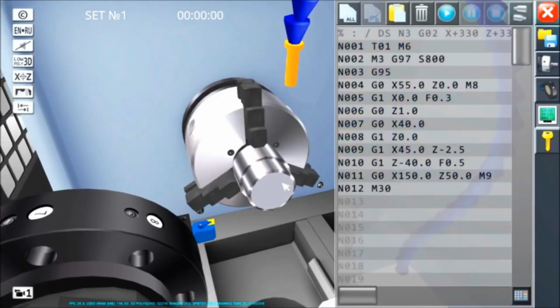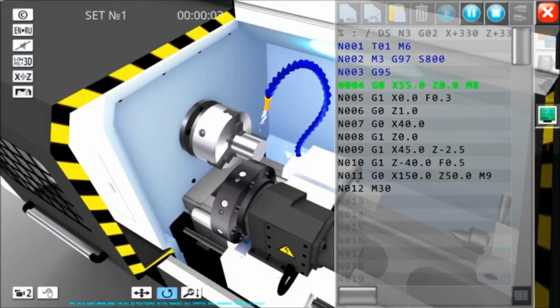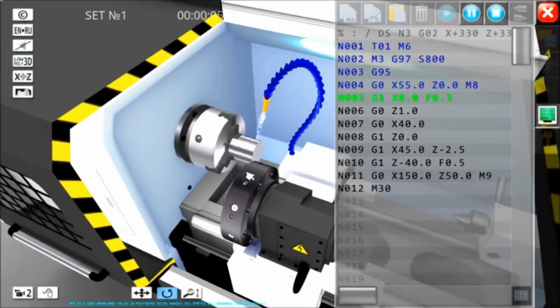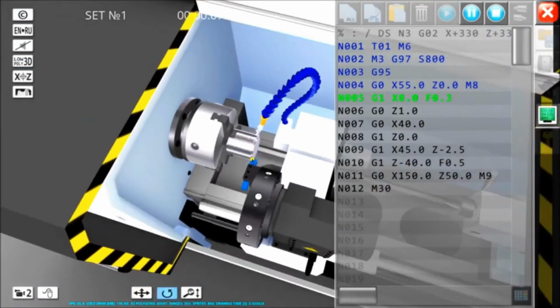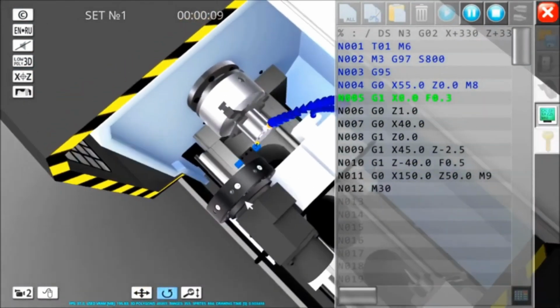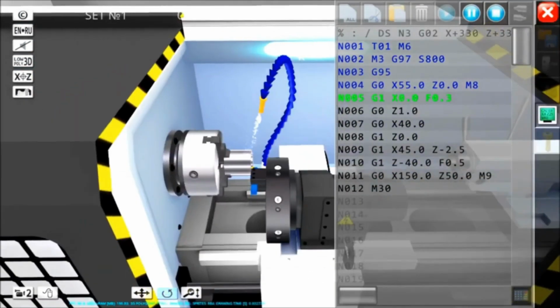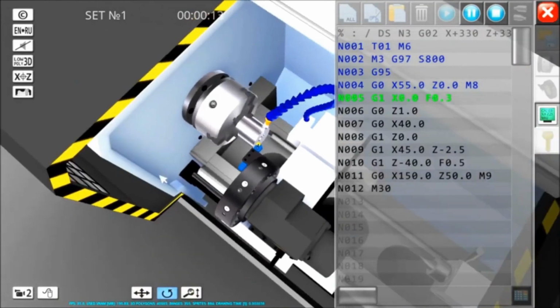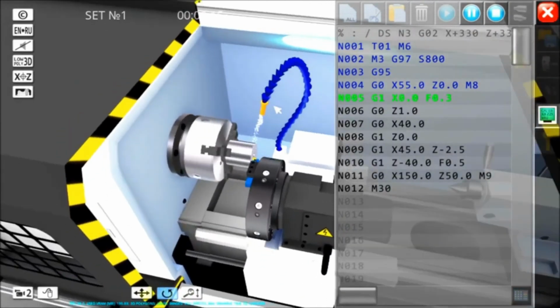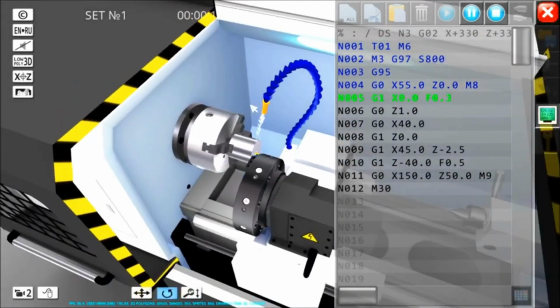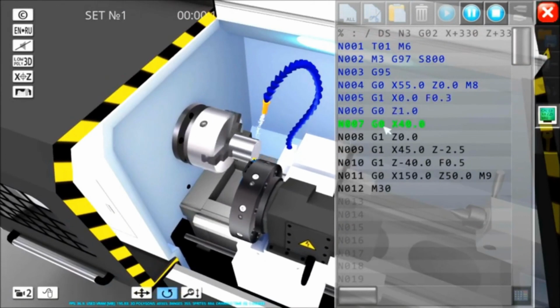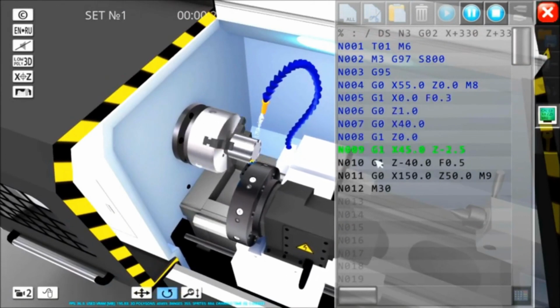You need to open and close the spindle, there'll be an M for that. You have to learn those by heart. Normally it's a good thing to put this list on the machine if you're going to do programming on the machine.